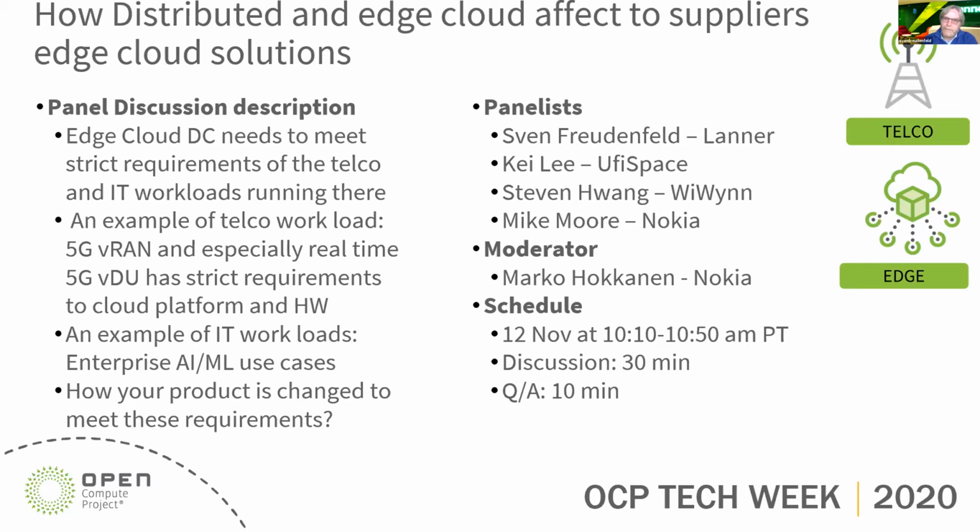The other key element we're integrating into this is the need for precision time protocol, meaning IEEE 1588, at the DU site, not at the disaggregated cell site, but at the DU site. So these are some of the elements that we have been considering on this.